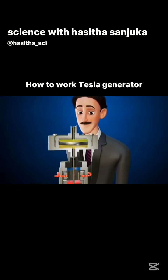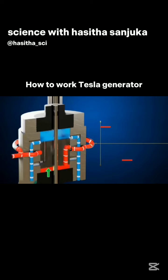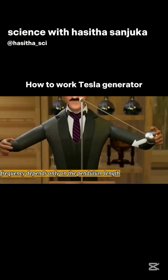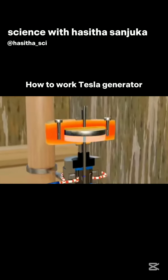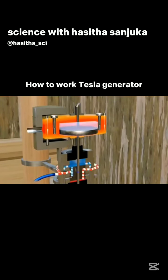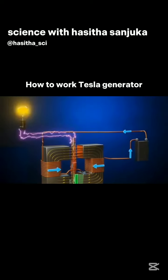In reality, the force acting on the piston is intermittent. The input of high-pressure steam is interrupted for a short period, similar to pushing a pendulum with both hands. Slightly increasing the force keeps the frequency constant, but the amplitude increases. Similarly, the greater the steam pressure, the greater the amplitude, but the piston oscillation period or frequency remains unchanged. Ultimately, the entire system operates at the same frequency, outputting alternating current at a constant frequency.